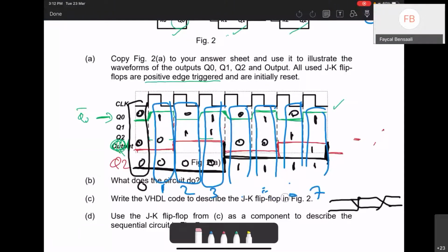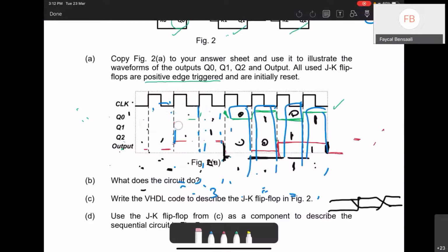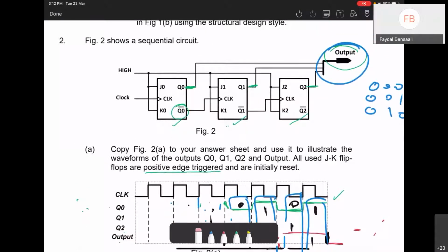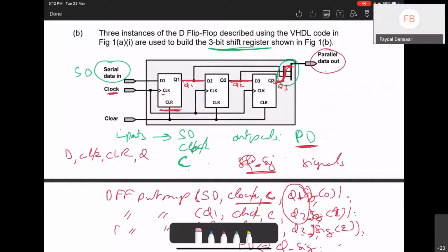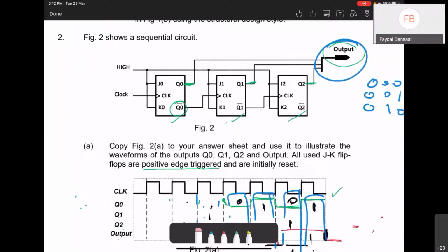Yes. And the circuit is very simple. I mean, we are toggling each time. The difference from one stage to the next is just which signal is used for the clock. So we are not using the same clock for all of them. Do you see, for the shift register it's the same clock for all of them. In this counter, it's not the same clock. So this is the original clock, and then for the next stage, we use the Q bar for the next clock. And then for the third stage, we use the Q bar from the previous one, and so on.